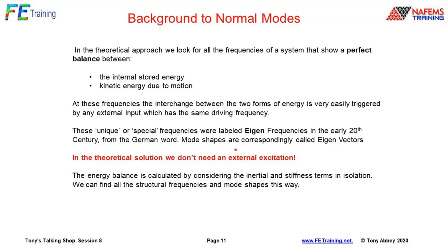So in a theoretical solution, we don't need an external excitation. So we can do it without having to define any form of loading. We need to have obviously the constraints in there, but we just look at this approach. And so we can find all the structural frequencies and mode shapes which are inherently there because we're not having to do a specific form of excitation. So it's a very, very powerful kind of technique.